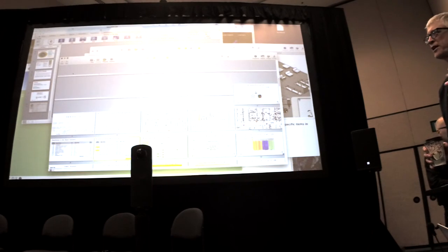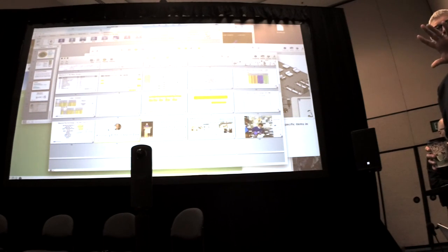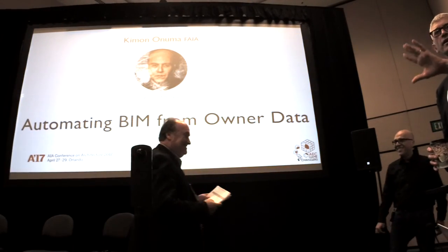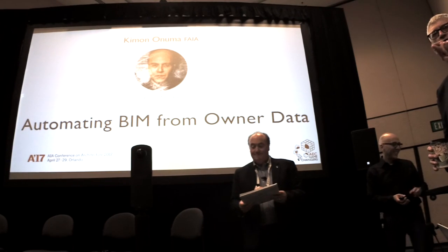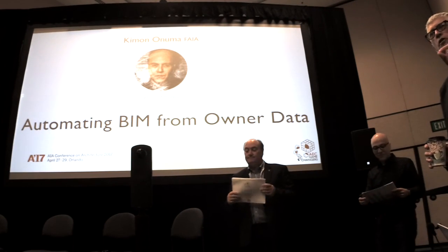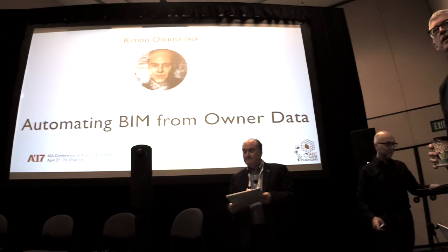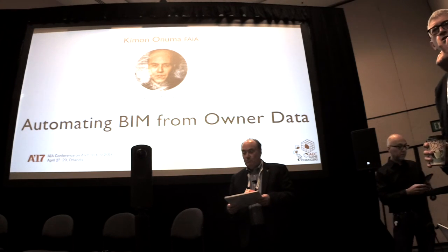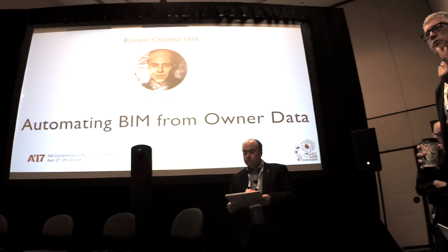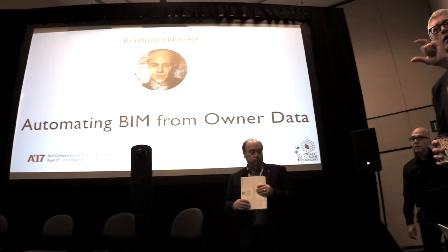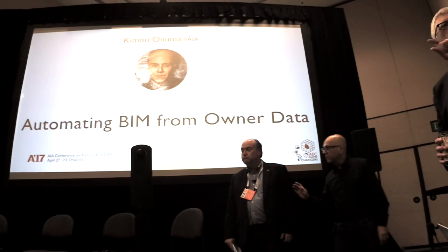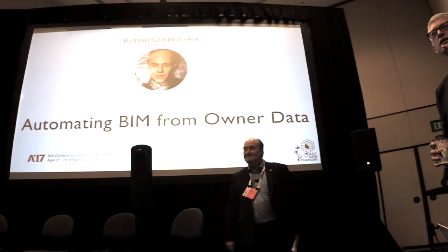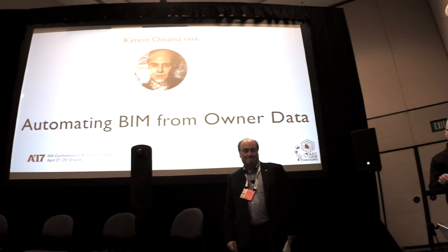Steve made me go too fast, but I was trying to talk about the analysis of that energy model. We found it was a beautiful model. Everything fits together and looks great, but when you get down to trying to use it for a specific purpose, there were all kinds of problems. The ductwork wasn't connected. It was all represented there, but it didn't connect all the way to the equipment, and the port wasn't established, so you couldn't tell which way the flow was. To do an energy analysis, you need to know the volume of the duct and the direction of flow. So when you get down to wanting to use it for a specific purpose, the model has to really be right, and you have to be clear about the requirements.